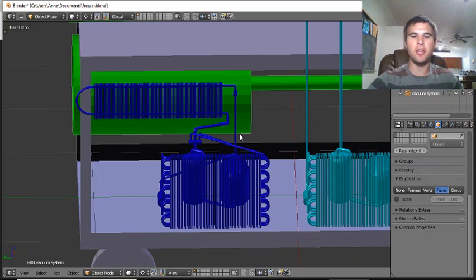Literally, you turn it into the heat pump, turn it on, let the compressor crank around for a few minutes until it actually achieves pressure and movement of the refrigerant, and that coil is immediately going to heat up to 150, 160 degrees. Then you shut the whole thing off and just let the heat that it's generated melt the ice, and then you just put a little drain valve somewhere on that and you could drain the ice.